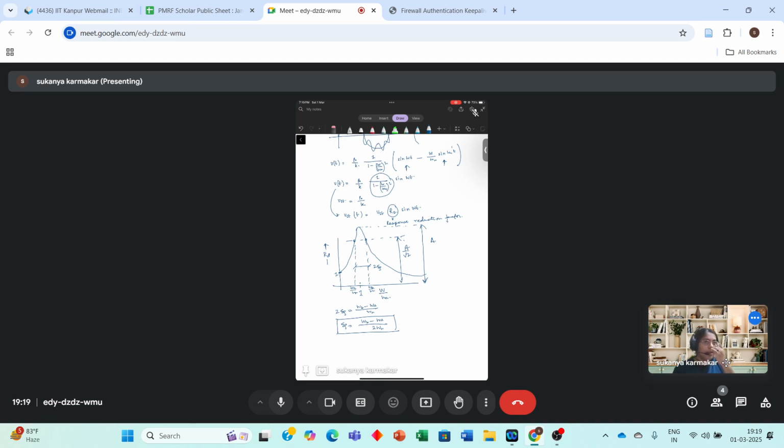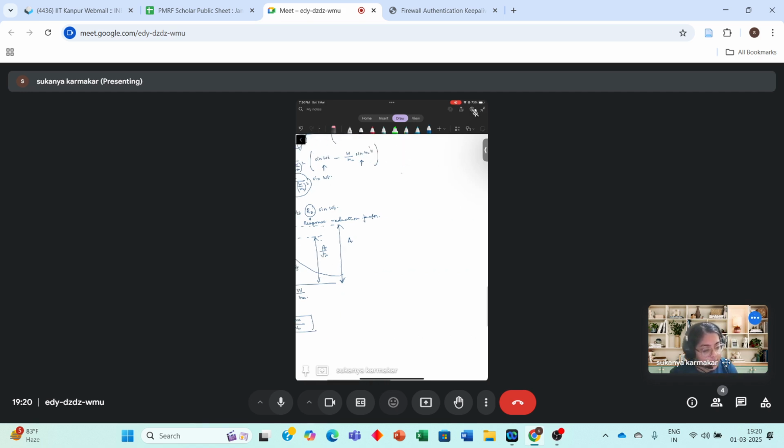But that is, see, the basic, I'll just summarize it very shortly. Suppose under earthquake, we don't want to make elastic structures. If we make structures to be elastic, the sizes will be extremely heavy, and it will be uneconomical, because of the probability of occurrence, under earthquake we are ready to accept some damage.